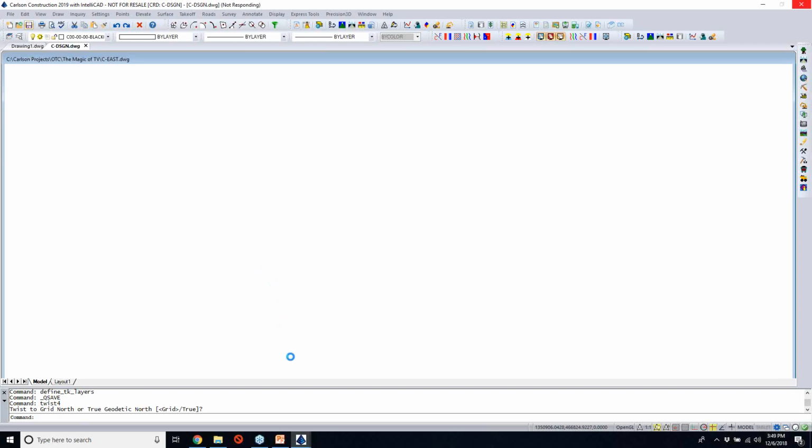Okay, so as we are going through this, I know again we're running just about out of time, but all the heavy lifting now is done because I've got everything all elevated. I've got all my contours joined. I've got my island set. All I have to do now is just pretty much say, here's the layers that make existing. Here's the layers that make design. Here's what I want to do for my adjustments. Make a couple surface models, calculate my volumes, and I'm pretty much done.